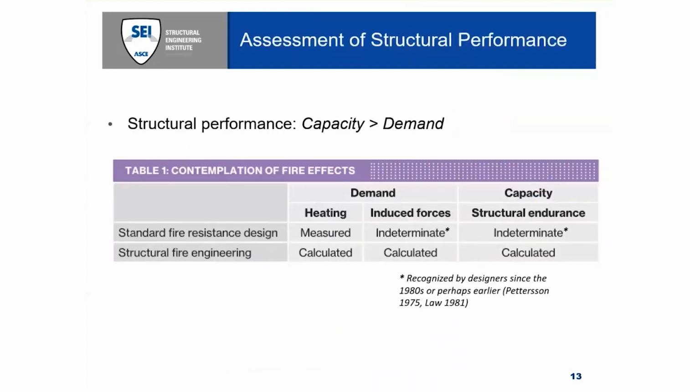So how is structural fire engineering different from standard fire resistance design? To start, let's examine these approaches in the fundamental design philosophy that we all appreciate in structural engineering, in which the capacity, both globally and locally, must exceed the demand implied or applied. As we discussed, standard fire resistant design is based on an empirical indexing system which excludes consideration of realistic thermal demands and structural system response.